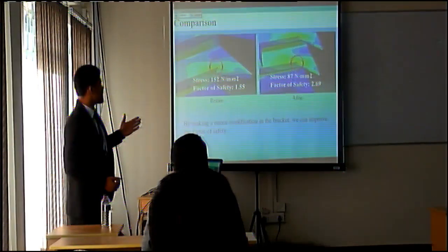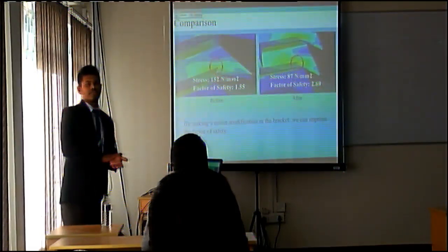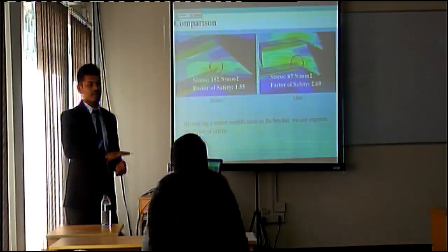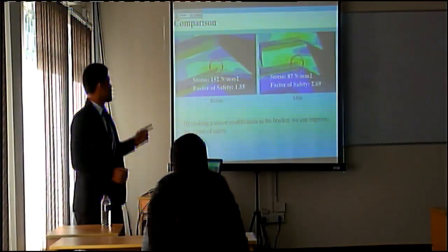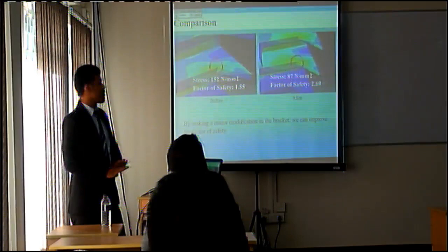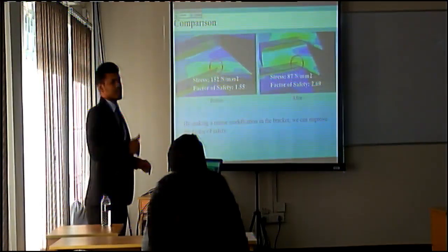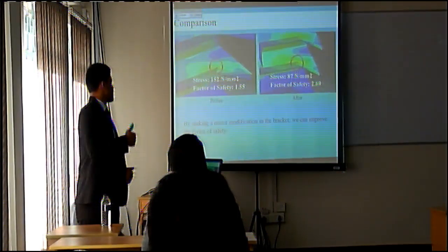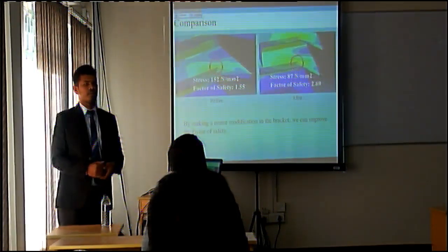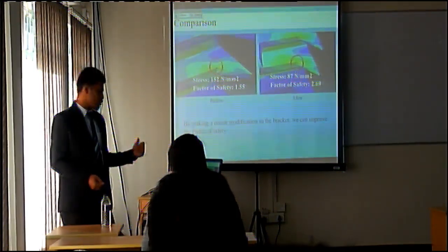Here we have analyzed the structure just for the joining of the horizontal stiffener and bracket, because the maximum stress always occurs in this region. There are many regions where the factor of safety is less than 2, so we can use this method of finite element analysis on those parts.